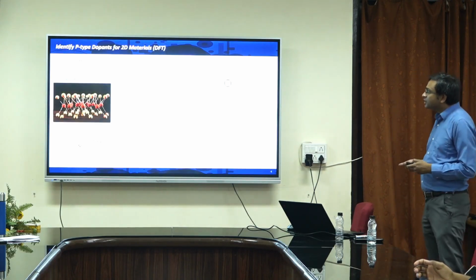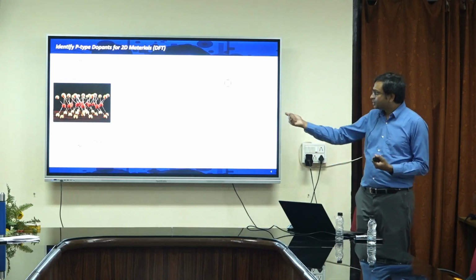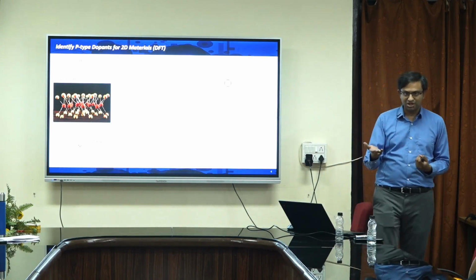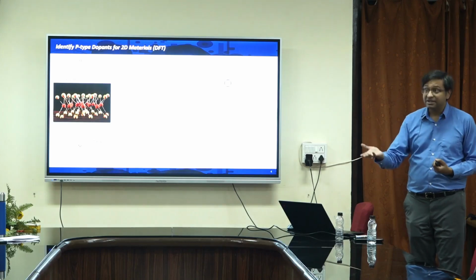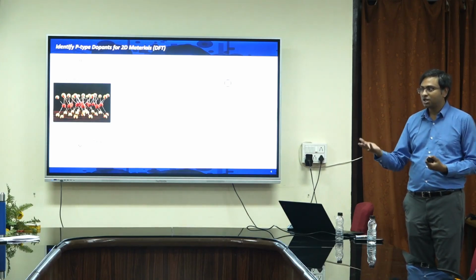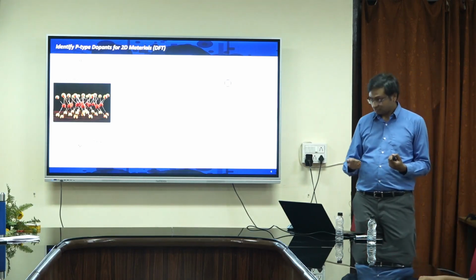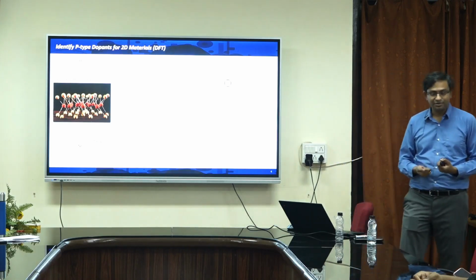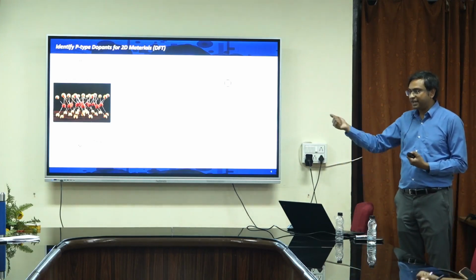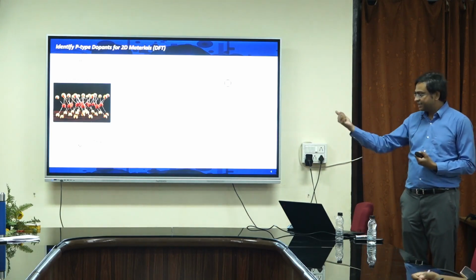So let's see. We search for the P-type dopant. You can do some DFT calculations, because you have to do substitutional doping, right? For example, for silicon, what is a P-type dopant? You guys know? What element of the periodic table should I choose for P-type doping? No, carbon you never use, right? So similarly, we have to find another transition metal which can replace tungsten and give me P-type doping.